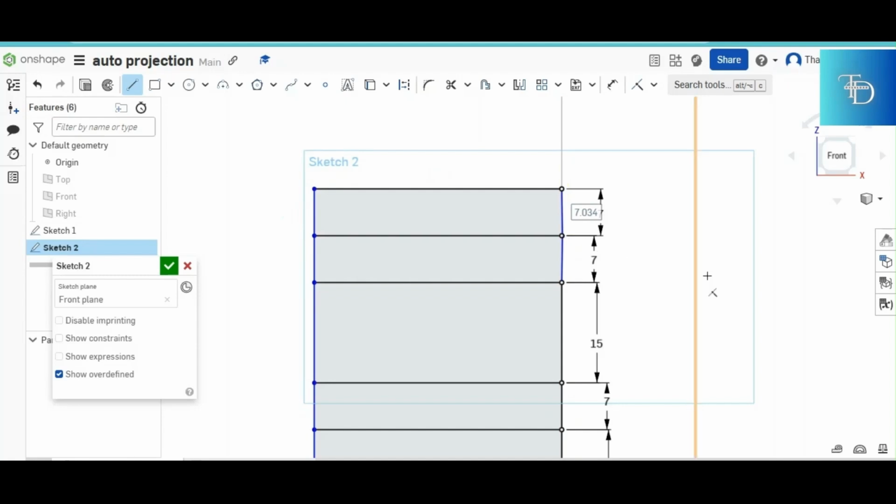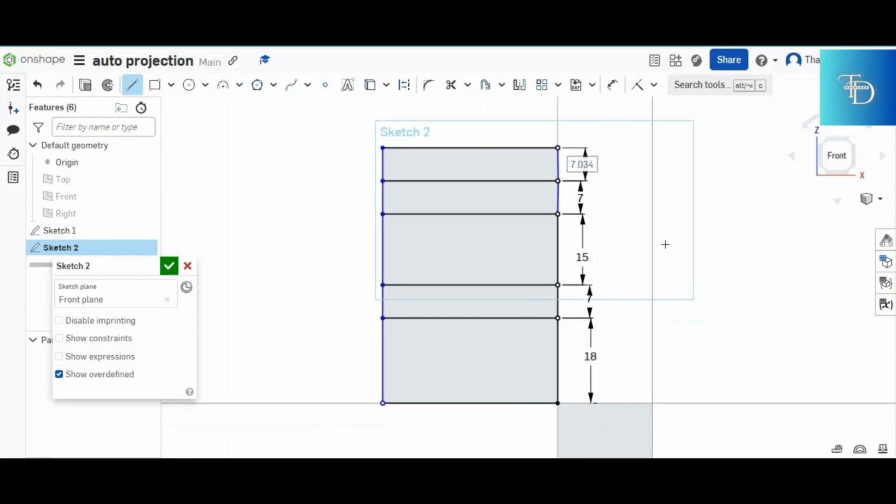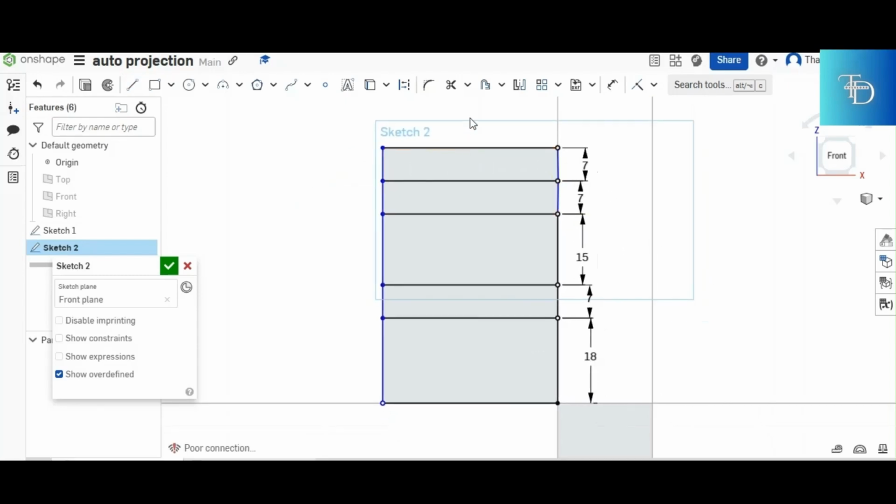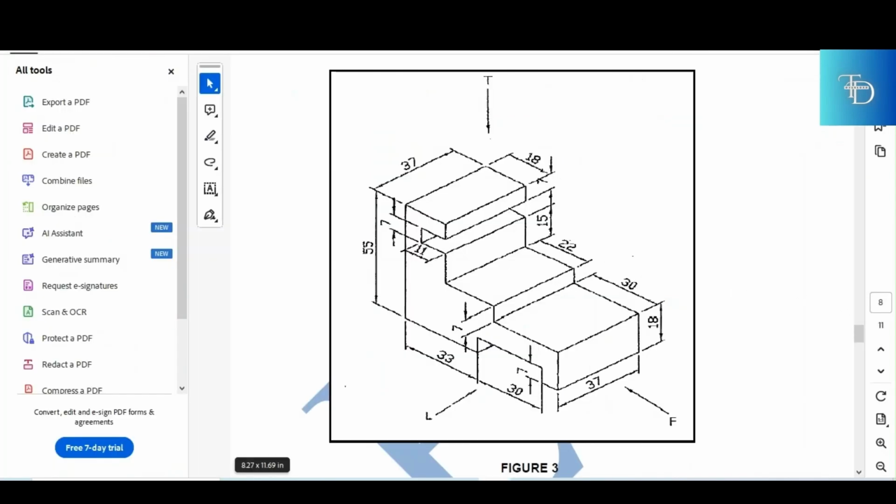Right there. You go back to your isometric view, you confirm your view. How many rectangular surfaces do we see here in our front view? There is one, two, three, four, five. You go back to your structure, you count your rectangular views. One, two, three, four with the hidden, and then five with the last. So now we can confirm that our front view is complete.